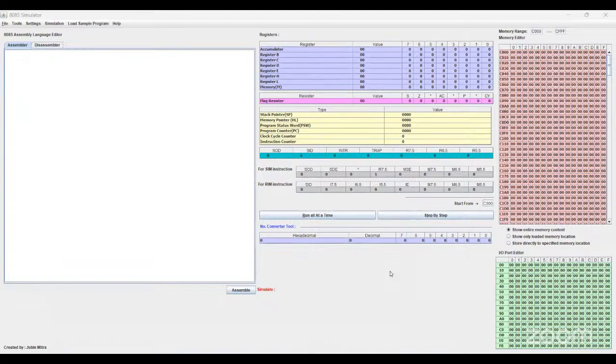Then there is an unconditional instruction. This will be used in subroutines. So CALL followed by an address, then it jumps to that particular location. This is used in the case of subroutines. And there are conditional call instructions also. These are call on carry, no carry, positive, minus, zero, no zero, even parity, and odd parity. So on these conditions also it will jump.